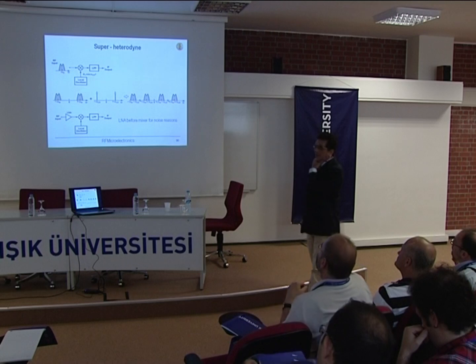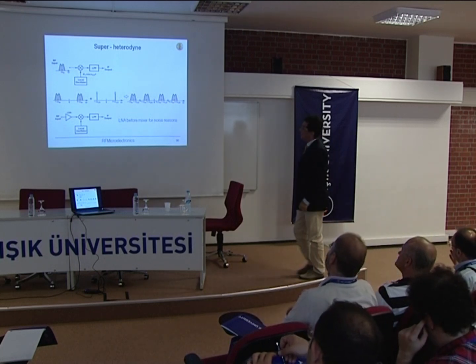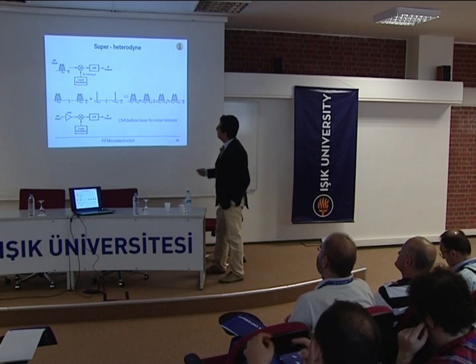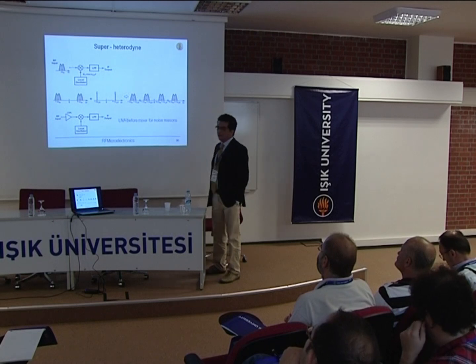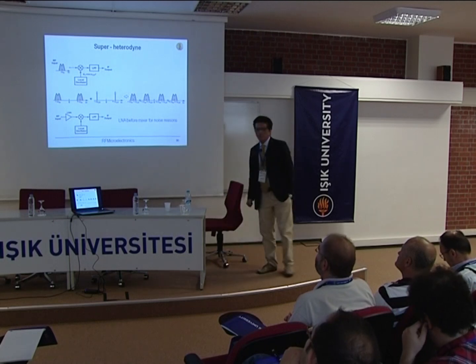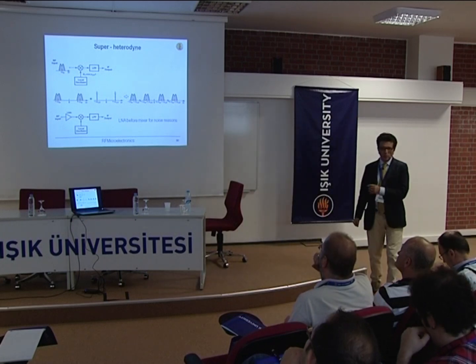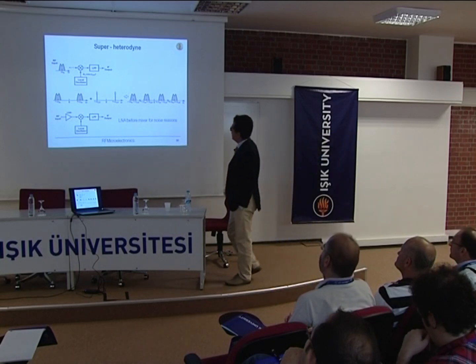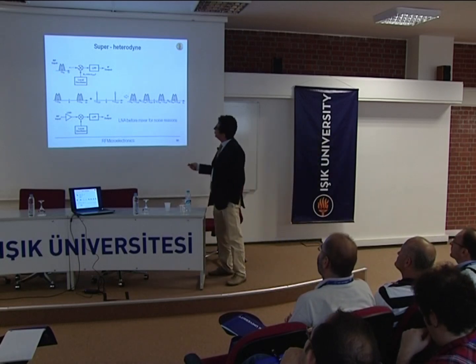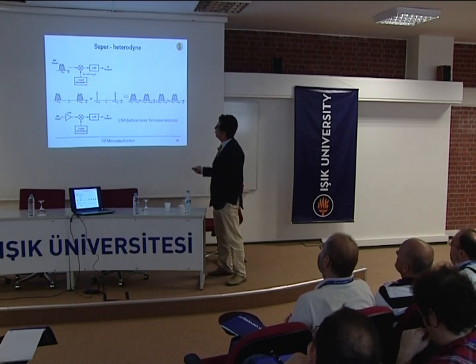So at this point, we understand that we will do something on the received signal which will not be selection, but some operation at RF frequency, and at some point we will need to translate and convert the received signal to a lower frequency. So at some point we will need an operation which is conversion to a lower frequency by means, for example, of a local oscillator.